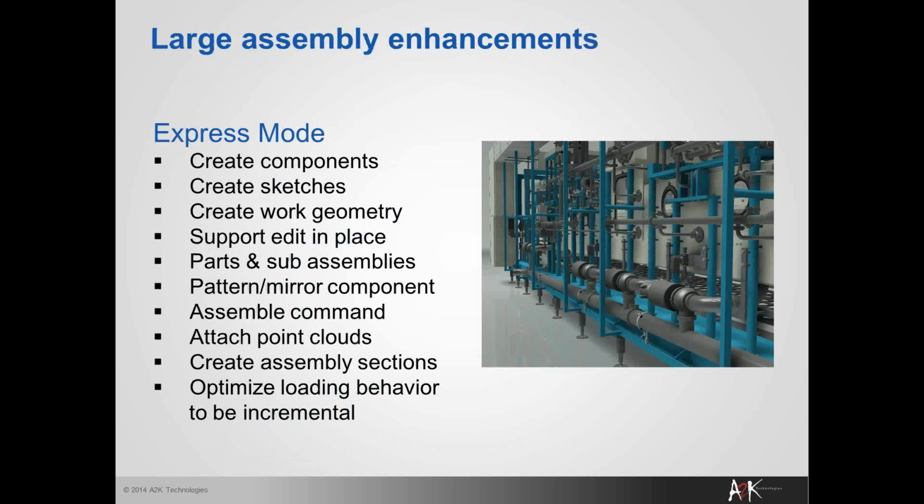You can now create components in place at the assembly level while still in Express mode, create sketches, even work geometry, supports edit in place. So while still being in Express mode, I can directly edit in place a sub-assembly or a part without having to load the complete parent assembly.